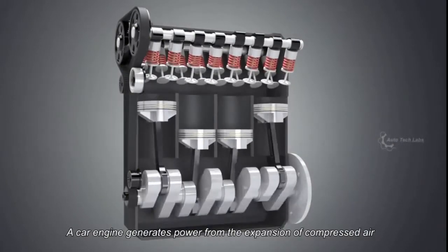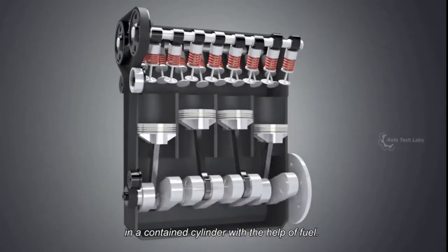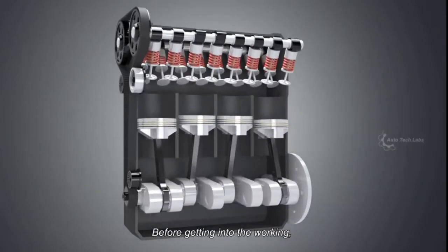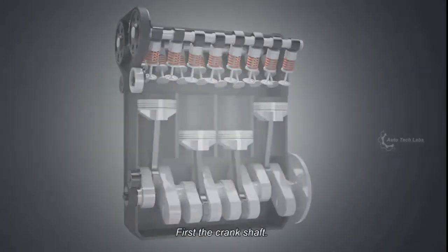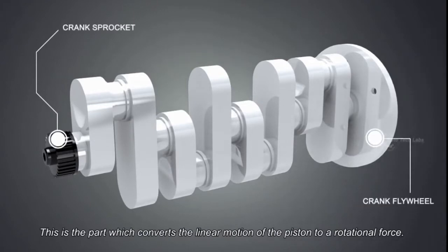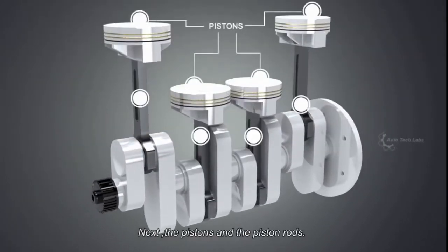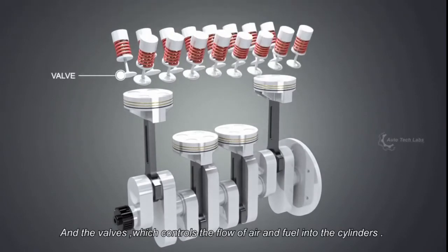A car engine generates power from the expansion of compressed air in a contained cylinder with the help of fuel. That is why it's called an internal combustion engine. Before getting into the working, let's see the main parts involved in the working of an engine. First, the crankshaft. This is the part which converts the linear motion of the piston to a rotational force. Next, the pistons and the piston rods. The pistons will be pushed down by the expansion of compressed air, and turn the crankshaft. And the valves, which control the flow of air and fuel into the cylinders.